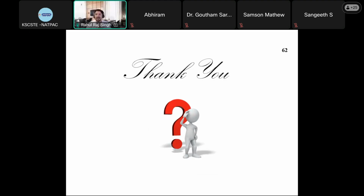Very good question. I have a partial answer to that question. I do not have the complete answer. First thing, the enhanced integrated climatic model that I just mentioned. There are a lot more things that I wanted to mention about Pavement ME and mechanistic empirical design, but I couldn't because of the limitation of time. This is what it does. It calculates for asphalt layers the modulus value at different temperatures. At the same time, it calculates the moisture content at different times of the year for unbound layers.